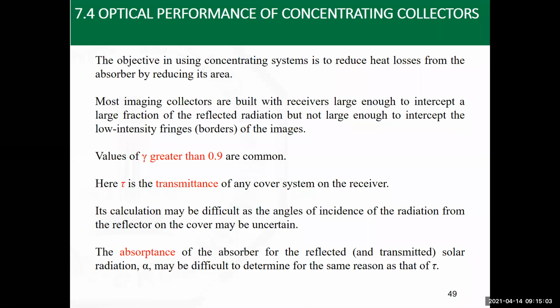We need to reduce the heat losses. This is why we are looking at the concentrator systems. This is why we started from the beginning, that if we are going to go for higher temperatures, then we need to reduce the surface areas in order to reduce the losses. And this is what we are looking for. So you would not get higher temperature accompanied by higher losses and lose the kind of benefit that you are getting from going to this geometry.